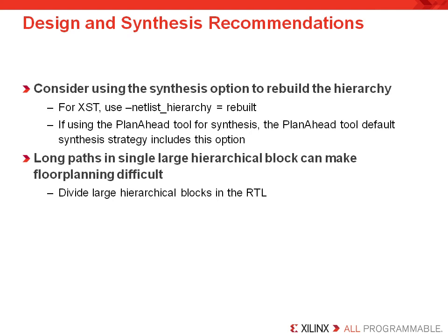Long paths in a single large hierarchical block can make floor planning a difficult task. Consider dividing large hierarchical blocks in the RTL, as it will be easy to work with smaller hierarchical blocks.